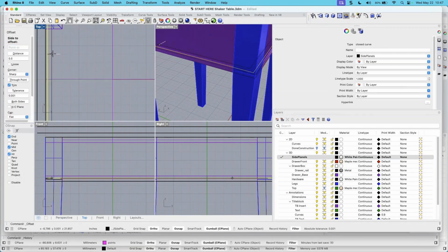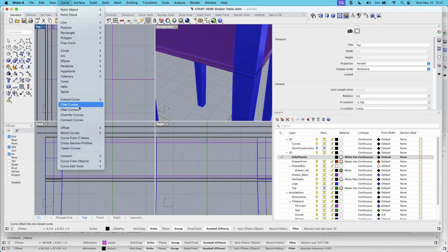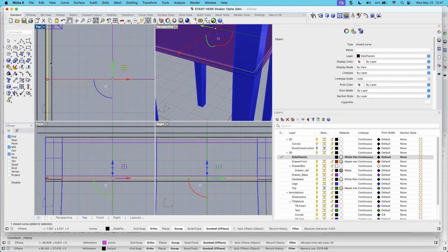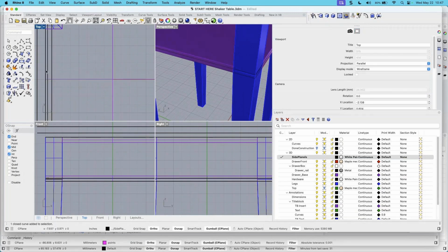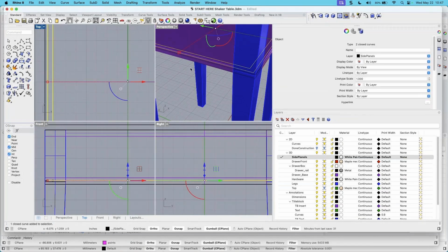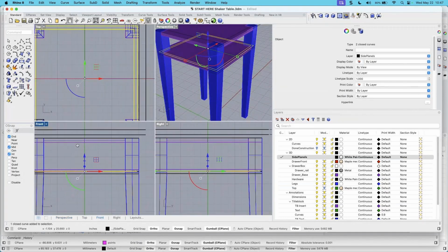And you can type in offset. You can pick it from the curve toolbar here. You can get to offset, but we took the original curve and we offset it by 0.25, and then this one from the new curve, it went at a distance of 0.5. And these two curves, the last two, are what I'm going to extrude into the side panel.